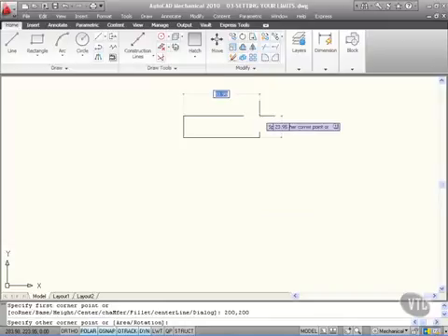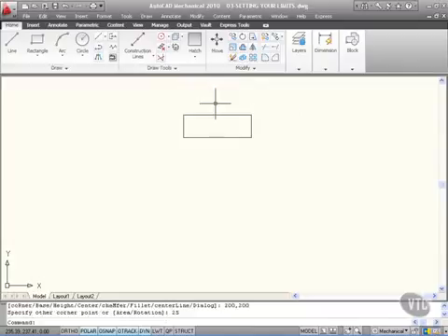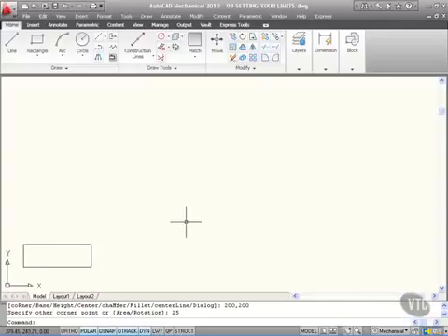Now it's going to be quite a small rectangle. Let's make it 75 millimeters along the x-axis, and then press the tab key. Height-wise, I'm going to give a height of 25 millimeters and press enter. So there's my small rectangle. Now, that started that bottom left corner at 200, 200. If I pan that down by holding the wheel and moving the mouse, that bottom corner is actually 200, 200 by way of millimeters and coordinates.